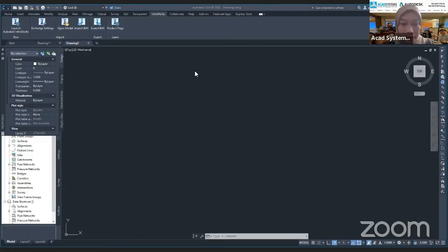I'm going to click on this bridge. Currently it is selecting the bridge. You can right click on it, and then we have Publish Civil Structure. This is used for exporting into both Revit and Civil 3D, these two software. Click on Publish Civil Structures, and then I'm going to create new.